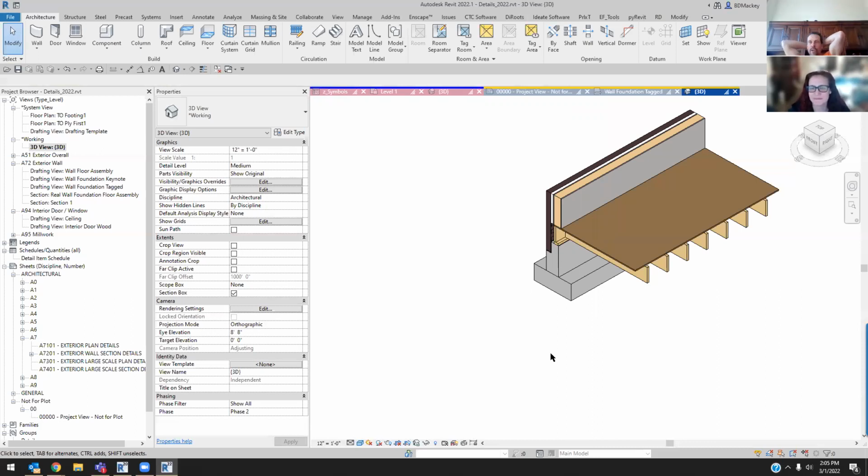So hopefully, I don't remember who asked the question on the binding. If you only need to bind certain parts of the model, because I do have a lot of interiors people that when they go to render, they bind in the architect's file in a rendering model so they can change the paint colors on the architect's walls. I have shown them that tool: you're only working on this one part of the building for rendering, so do a 3D section box, save that, put that on a sheet, save that to a Revit file, link and bind that in. And they were like, yeah, that just saved us days worth of work. Thank you for that.